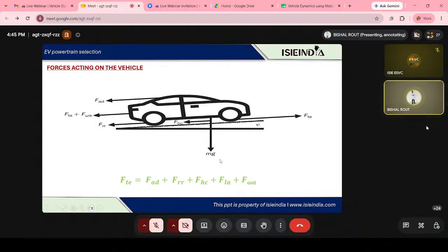Right? Yeah. So where is the tractive effort force generated from in the vehicle? Inside your vehicle, you have a motor and a battery. The battery provides current and electricity to the motor, and the motor generates the force, and using that force the vehicle gets torque, right? Now the question is: what kilowatt motor needs to be installed inside a vehicle so that it can generate that much torque, so that the torque generates the required force that needs to be calculated? For that we need to calculate how much force is actually opposing the vehicle. So F_TE is called the force due to tractive effort.